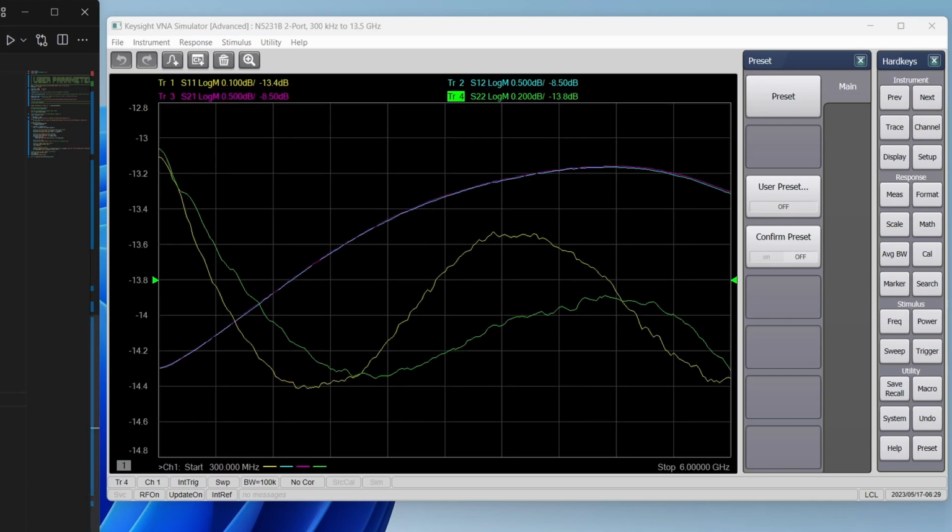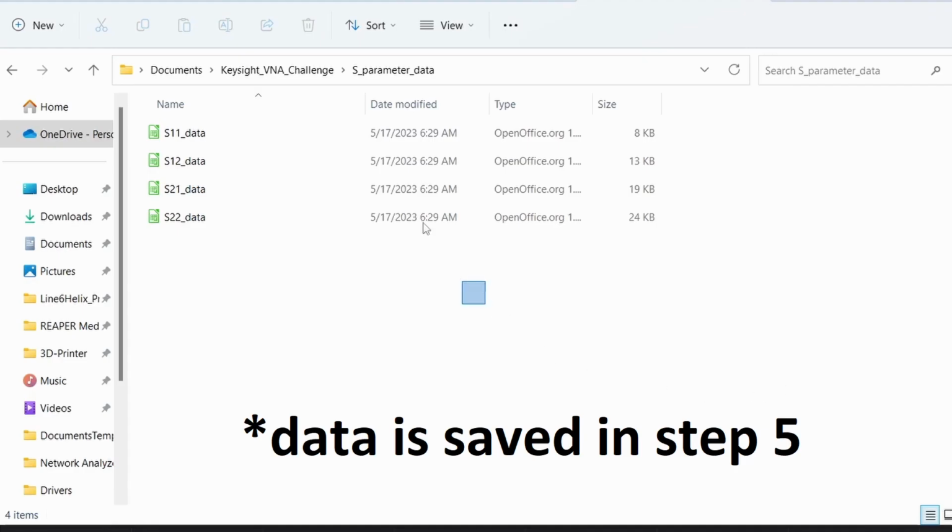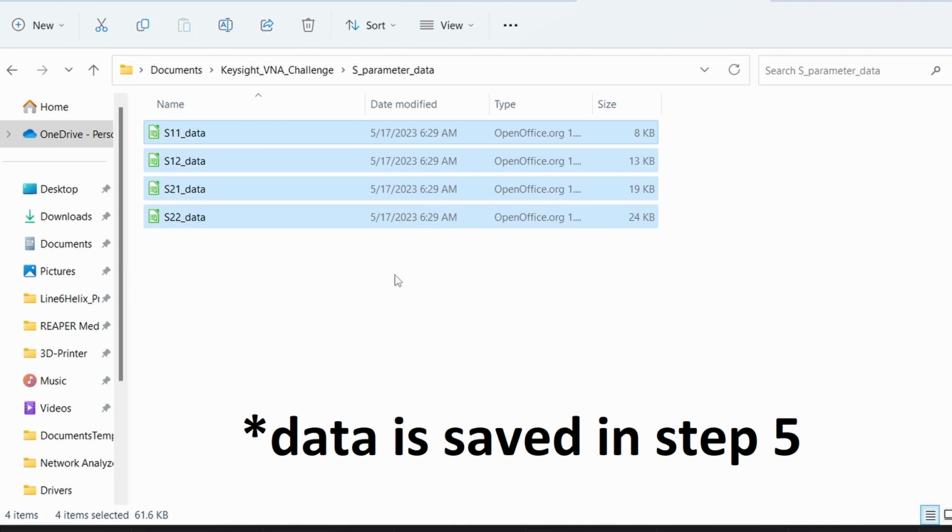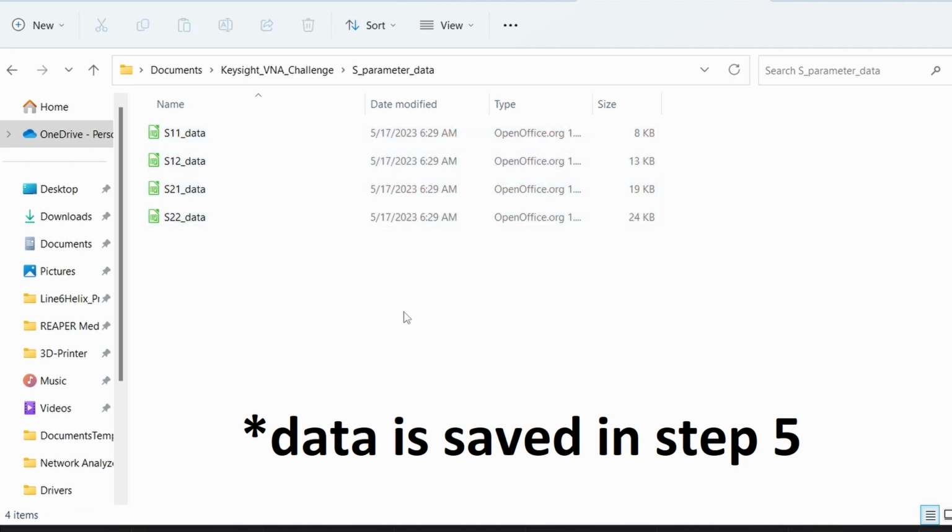And now if I run my Python script, we will see a few brief flashes and then all the traces will be on. Having a decent automation environment enables rapid validation of components by allowing us to simply connect our new devices to the VNA input ports and to run the same automation script that we've had before.